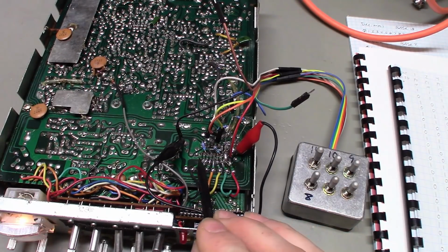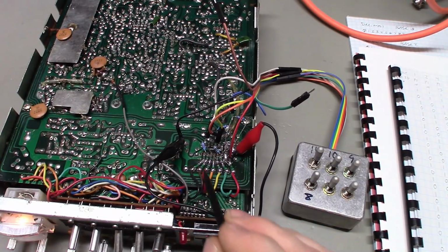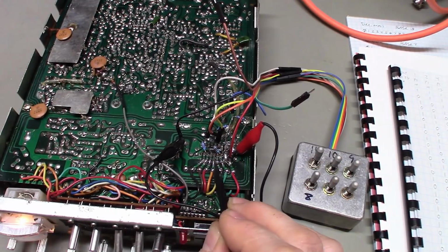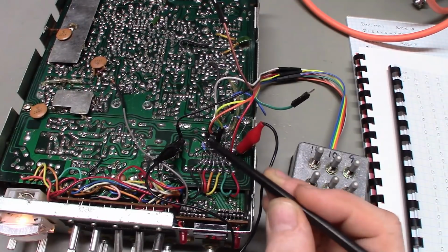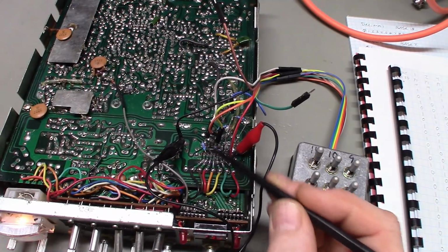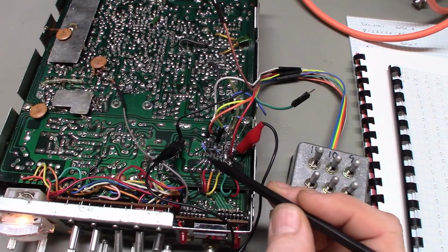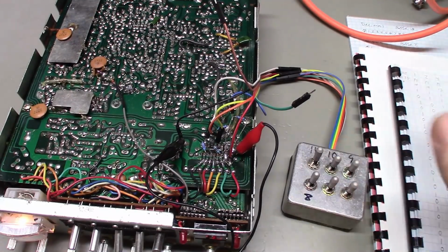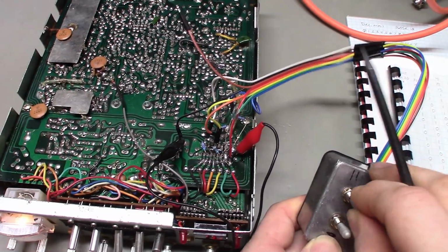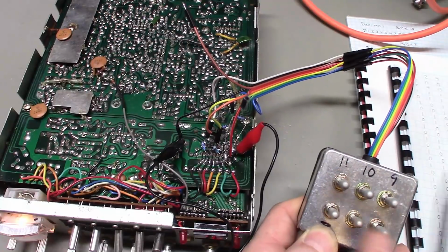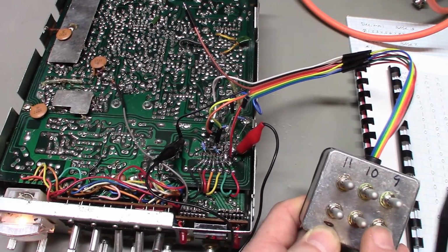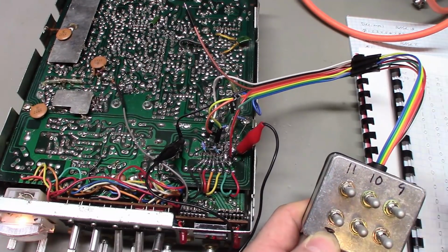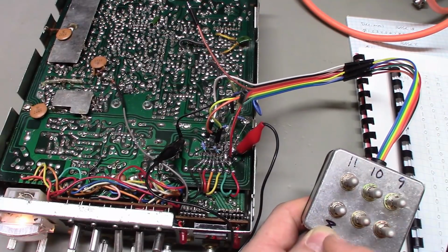What you do is you cut the circuit traces, which, like I say, this one had all of the traces cut. You cut the circuit trace, and you jump across that cut with a resistor. In this case, like I say, I'm using a 3.3K resistor. Okay, so in the way I have this box set up, in the center, that's why I use 3 position switches, in the center, these wires are not attached to anything.